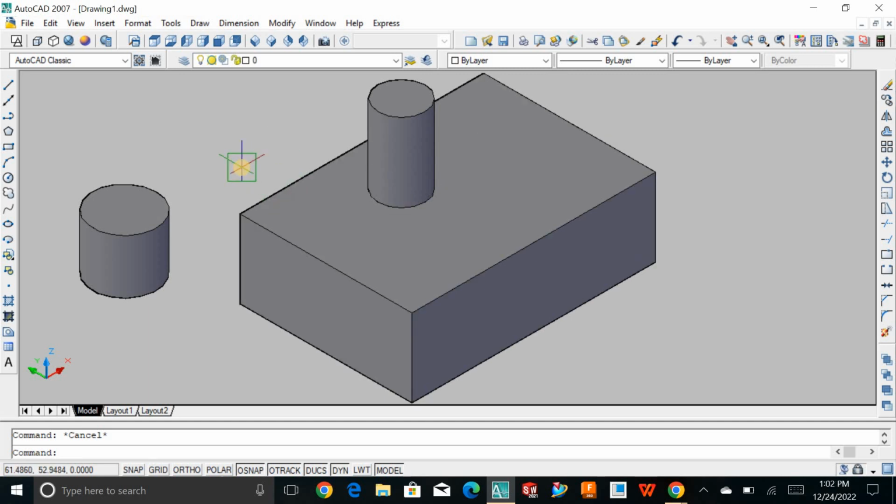Now most of the time we don't want it in this direction. So how can you change and play around with your UCS? This is really the tricky point. If you know this, I think 3D is not really a critical problem for you. So if, for example, I just want to extrude on this face, I must change the direction of the Z this way, right?